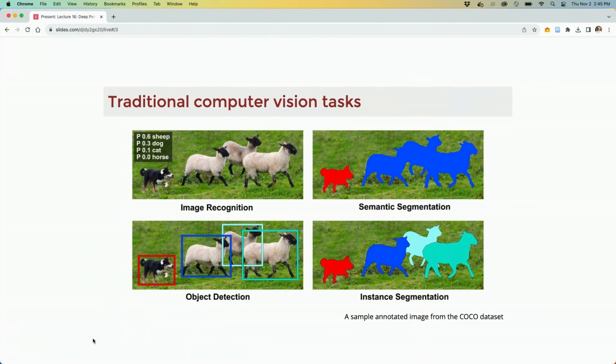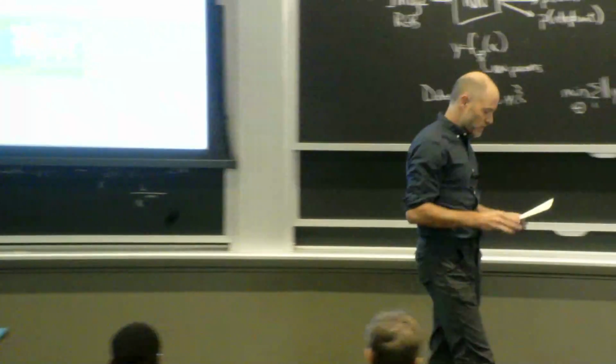Actually, another thing that people commonly did when this started to work really well was they'd do that same beginning of the pipeline. You'd take your RGBD images, extract out the ones that mattered, and then maybe if you had a known model of the mustard bottle... Remember we said ICP, the iterative closest point algorithm, didn't work if you just give it a messy scene and ask it to find the mustard bottle. You've got no chance, okay? But if you segment out just the pixels of the mustard bottle and now run ICP, then segmentation plus ICP is a pretty powerful pipeline for pose estimation. We have better pipelines now, but that was right out of the box a pretty good thing.